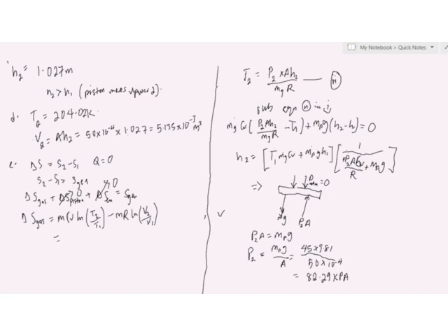This is CV, which is given, the specific heat capacity at constant volume, ln natural logarithm of T2, the calculated T2, all over T1, which is given from the question, minus the mass of the gas multiplied by R, the molar gas constant, given also from the question, ln V2, this calculated V2, all over V1.